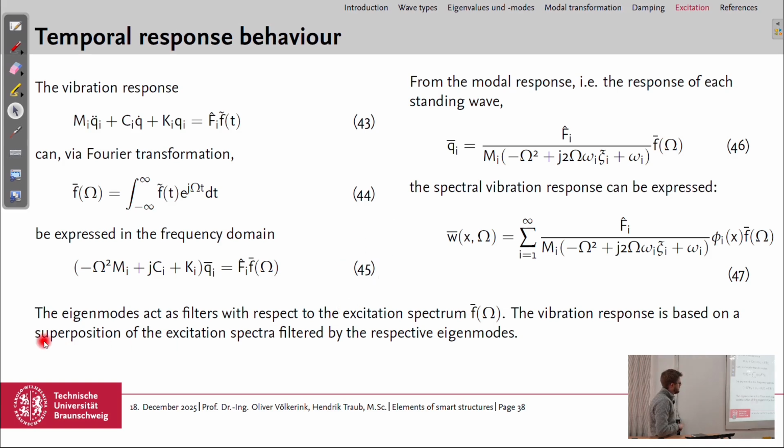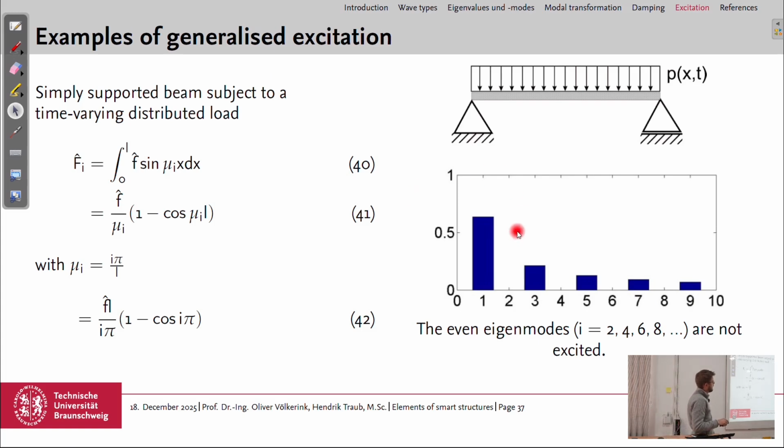And we can state by this that eigenmodes act as filters with respect to the excitation spectrum. So the vibration response is based on a superposition of the excitation spectra filtered by the respective eigenmodes. And this can also be seen here. We have a general excitation, but the eigenbehavior of the structure filters the excitation so that only the odd eigenmodes are excited.